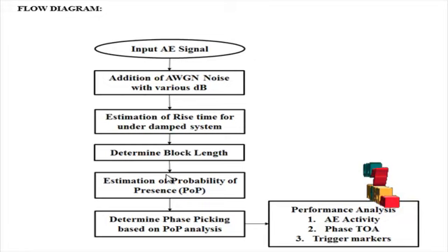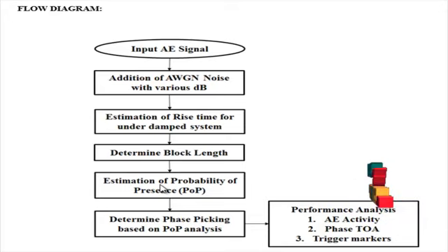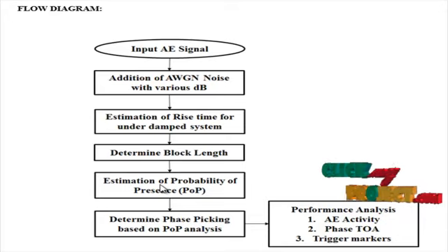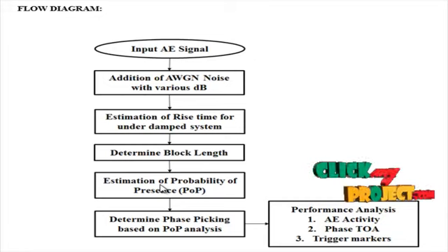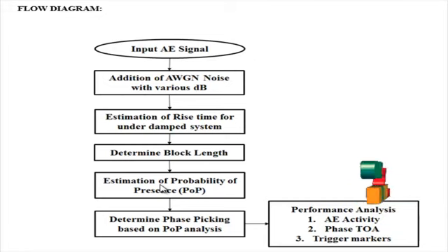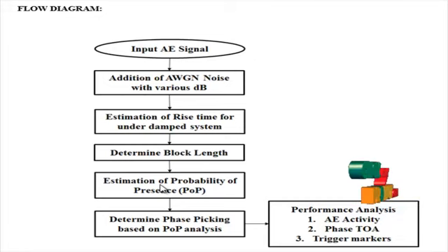The estimation of probability of presence: signal presence probability from the estimation of clean speech spectral coefficients in a signal enhancement task using both a fixed a priori signal to noise ratio and a fixed a priori probability of speech presence. The proposed posterior signal presence probability estimator achieves probabilities close to 0 for signal absence and close to 1 for signal presence.